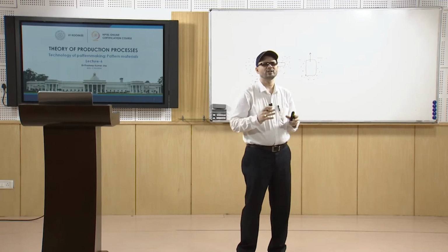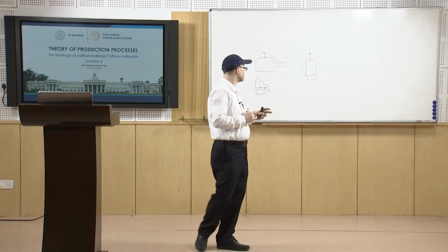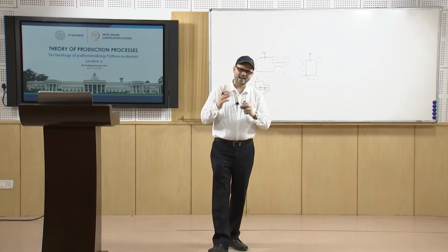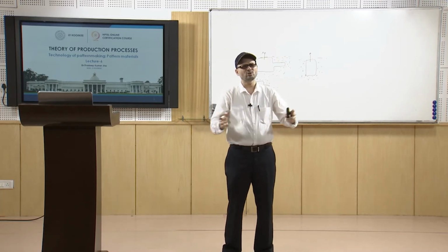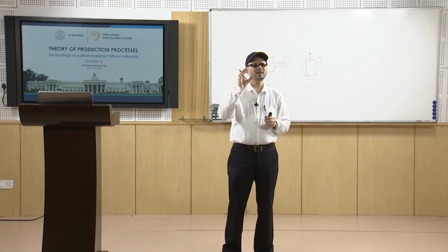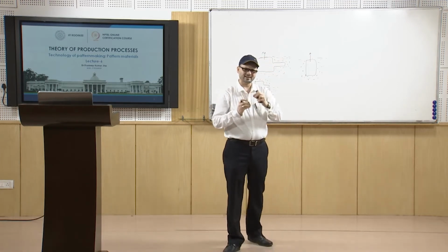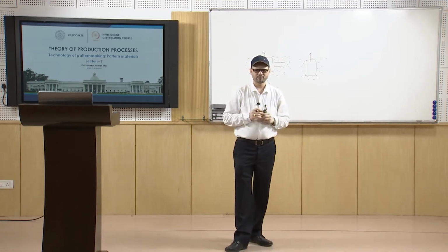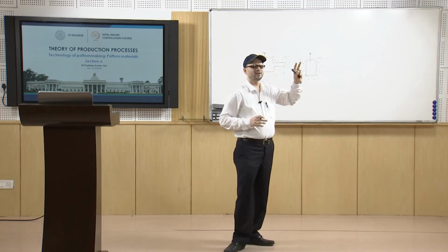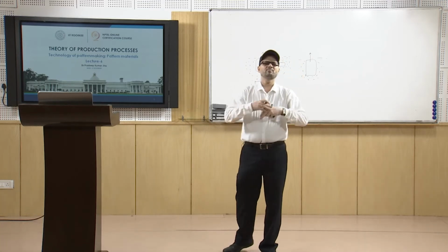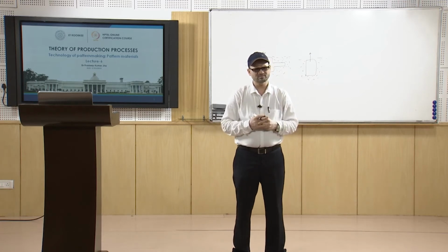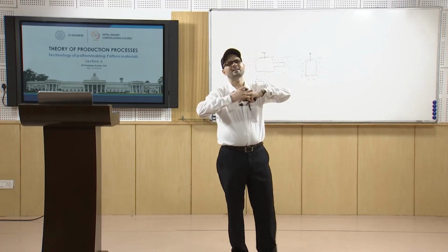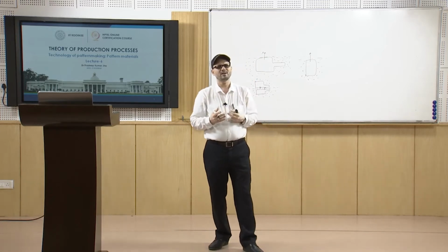Many times you are using it in a very harsh atmosphere, or with sand used for long, which erodes it from the sides. So, based upon the conditions in which you are working, if you are using it for a very long run, for many lakhs of units, then it is better to go for metallic patterns, because that will be long lasting, and its life will be larger.